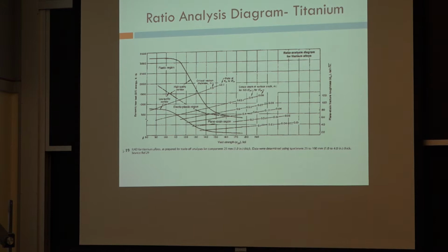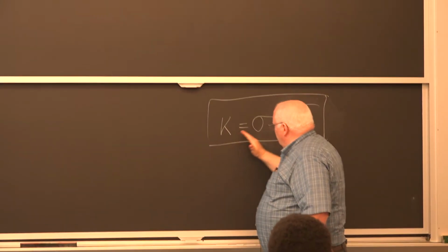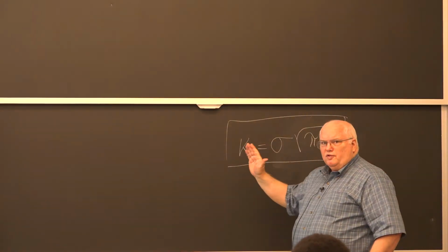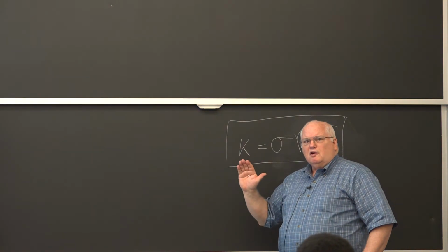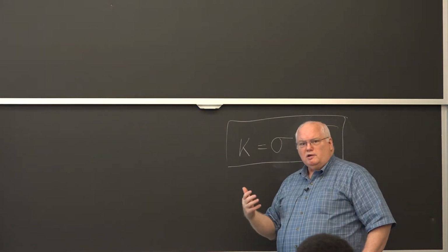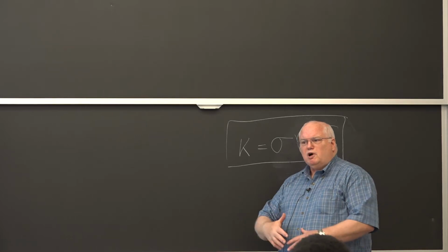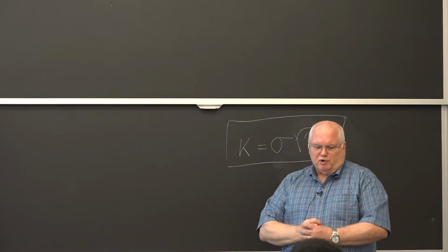And he's considered the father of fracture mechanics because he took this idea that Griffith had, that you could study the fracture of a brittle material like glass, and you come up with this. I put it up the other day. The fracture toughness is equal to the stress times the square root of pi c. That's the fundamental equation of fracture mechanics. Came out from Griffith in 1925. Everyone thought it only applied to brittle materials. Irwin showed it also can be applied to ductile materials. And so it's much more general than just brittle materials.